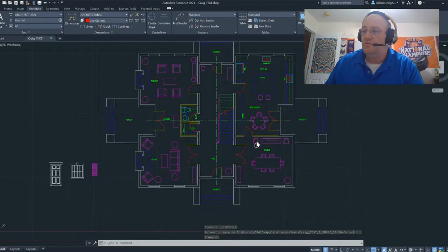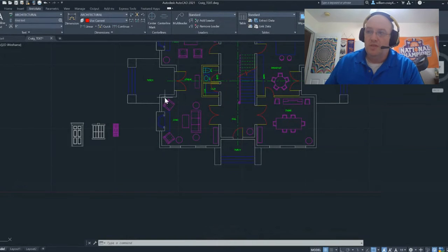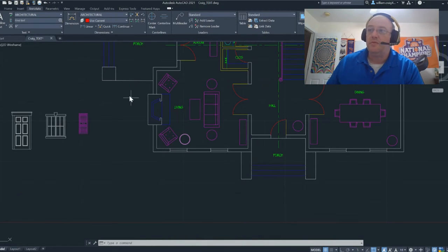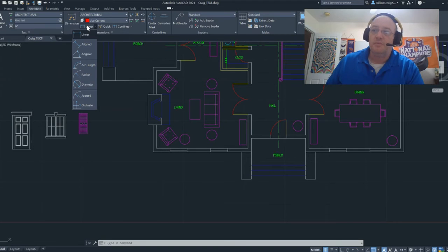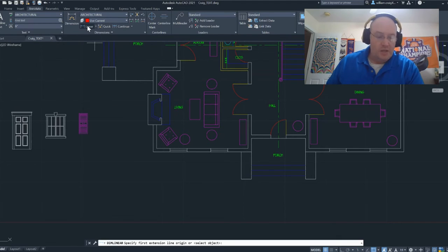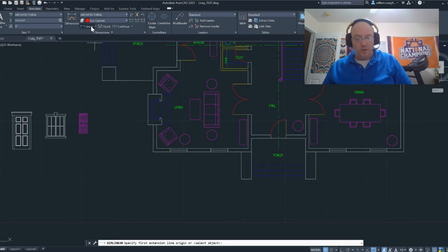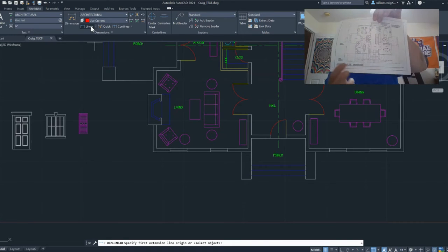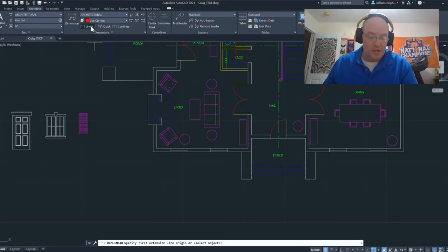So, really neat thing. We can do horizontal, we can do vertical dimensioning. I'm going to come over here. I like to do this off the Annotate tab because I do have all of my options sitting in here. So I can come with a linear. I do have other options here, but I'm going to go with linear. And at this point, really what I am going to be doing is starting to work right off of this here and just kind of working across.